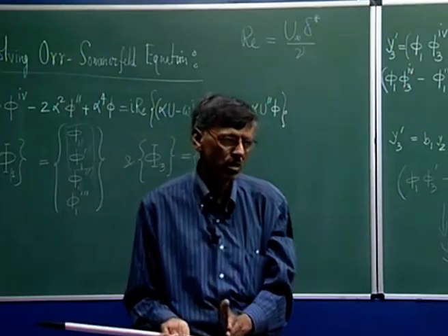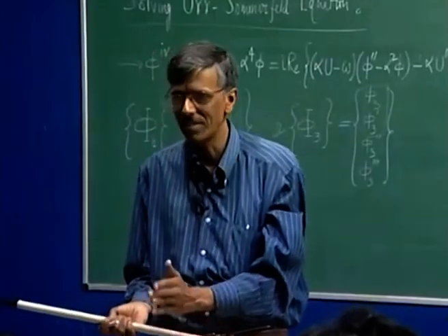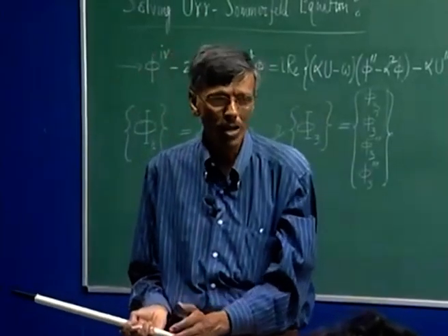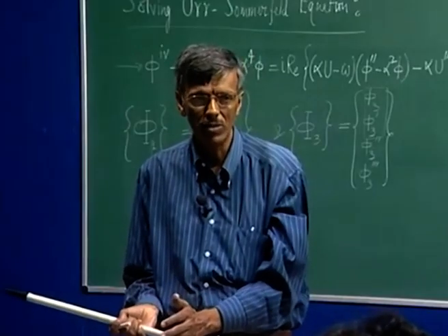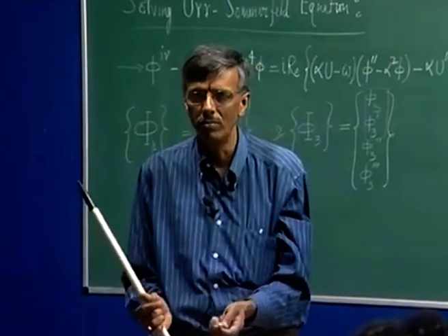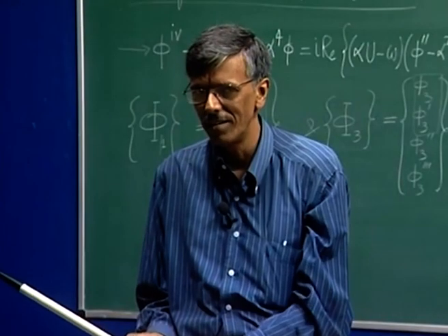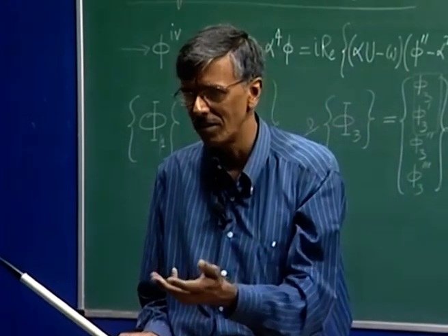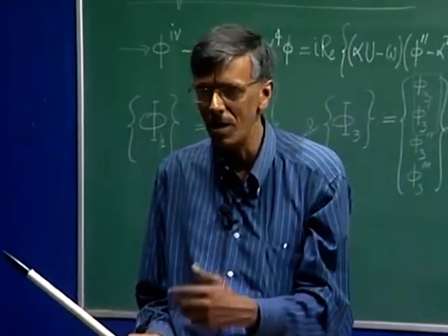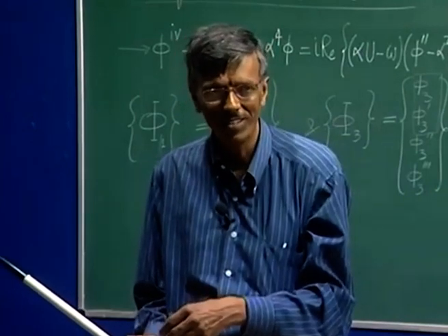We want to, let us say, study the spatial stability problem. So, we also fix omega, that is a real quantity, right. Now, what are we after? We are after a complex value alpha, that is what we will have to do. So, we will choose some value of alpha and then we will solve those 6 set of ODEs, come all the way up to the wall, and if we see y 1 is equal to 0 there, then the guessed alpha was the correct eigenvalue. If it is not, then again we will have to conduct the search.